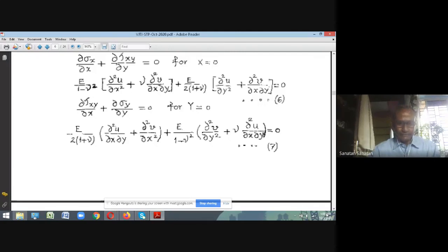So you get the extra equation to overcome this statical indeterminacy. In the strength of material problem, u1 equal to u2, so you had to determine simply one displacement u. Here, making use of the compatibility conditions, the equilibrium equations simply boil down to two second order partial differential equations involving the u and v functions.